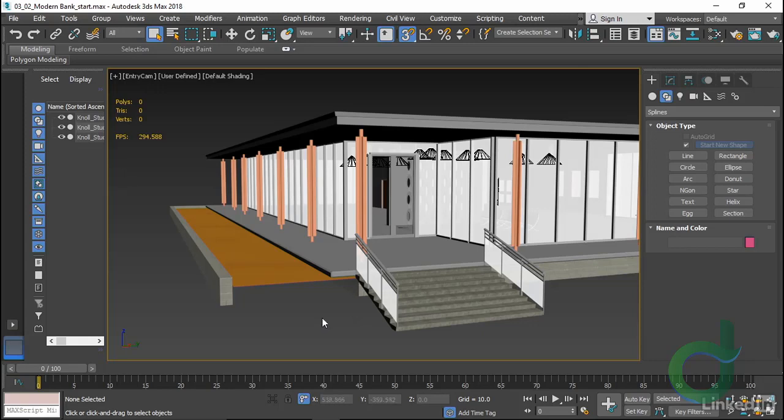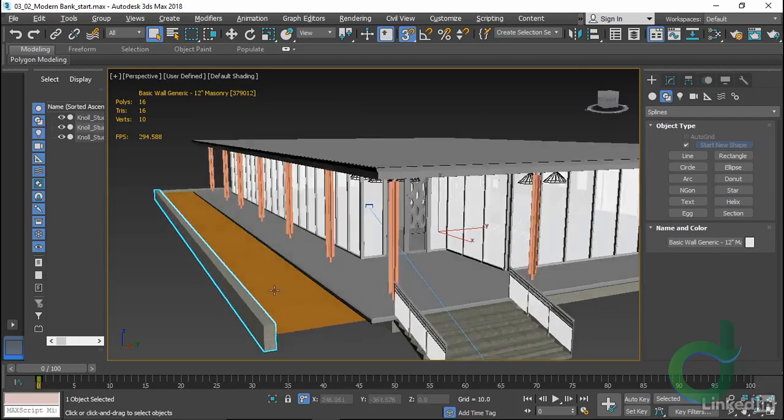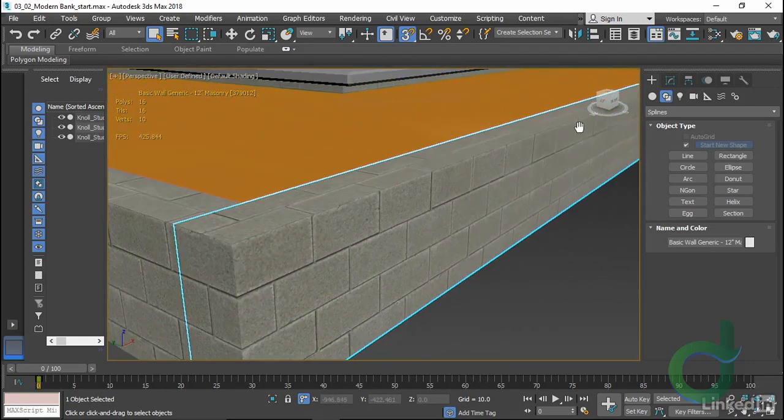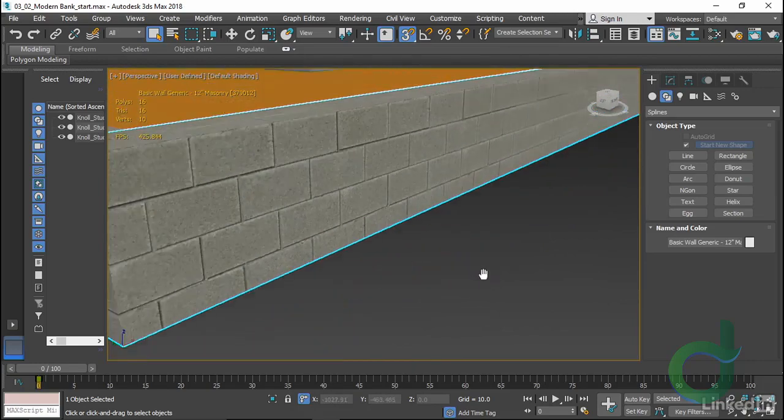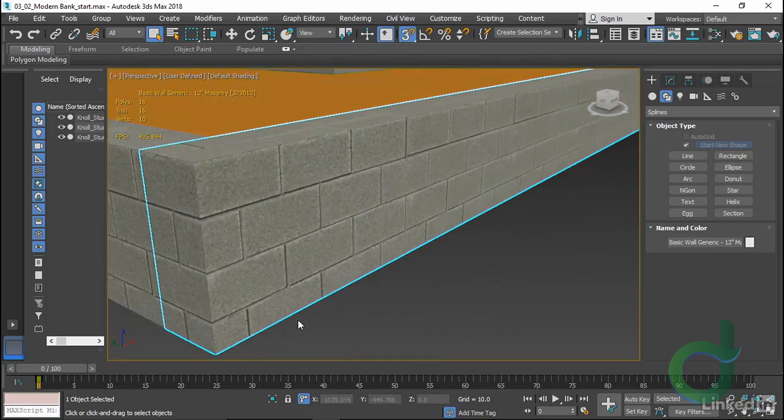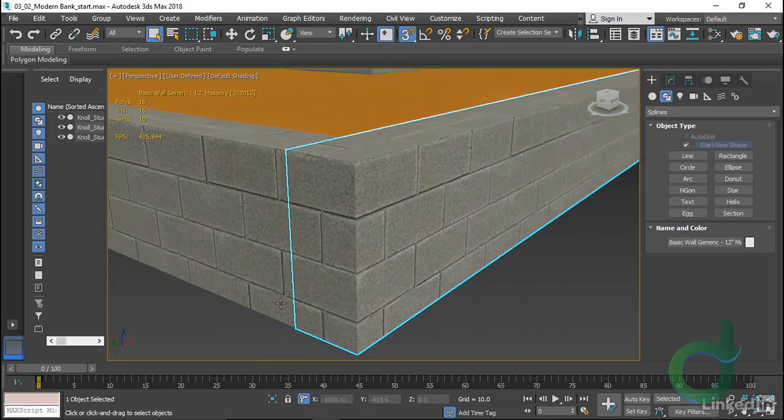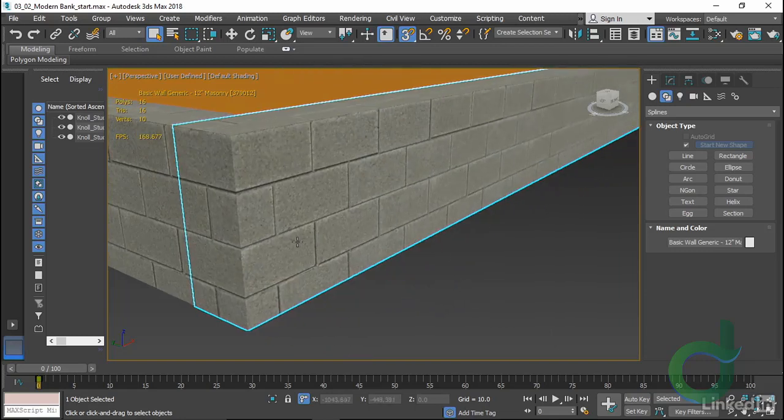We've got terrific tools, and I'm going to go through and do a little bit of remapping on some of my block walls. I'll pick one of them and hit P for perspective and orbit around. It looks decent, although there's some things I'd like to change. We've got the right number of blocks tall, but right here on the corner I'd like this texture to wrap around better. Also on the top, I either need a cap texture or a separate cap material, or maybe even separate cap geometry. What I'm going to do is to get the mapping flowing around this corner nicely first, and then see how I want to make it work on the rest of the wall.